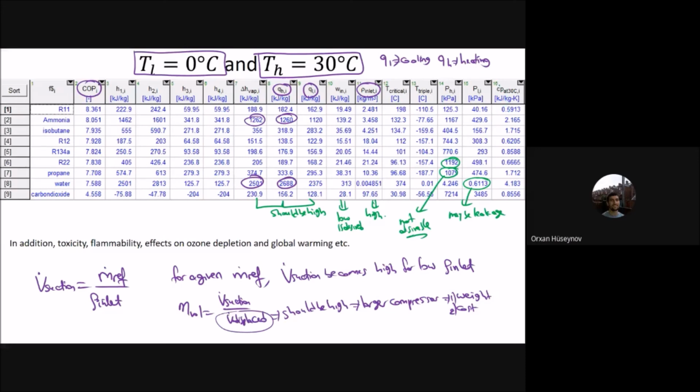This CP value should be high. Okay. And why should it be high? Because if it is very high, it means that the temperature will not change even if it accepts lots of heat. For example, water is used in chillers. What we use in chillers is that water has a very high specific heat value, and therefore if it changes the temperature of the room, for example from 25 degrees to 40 degrees Celsius, its temperature doesn't change enough.